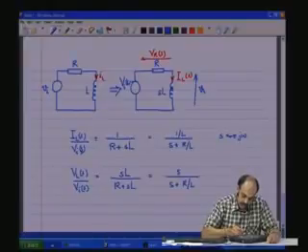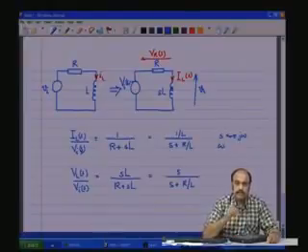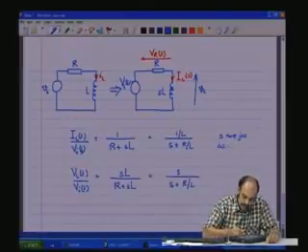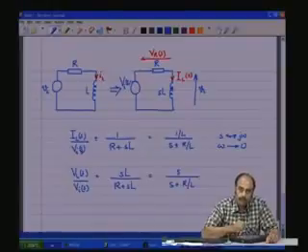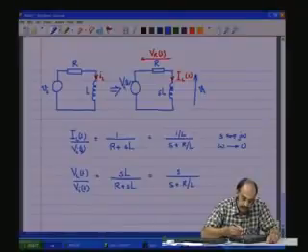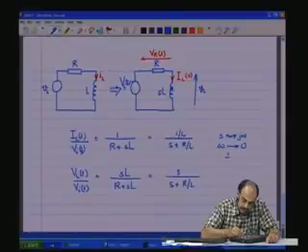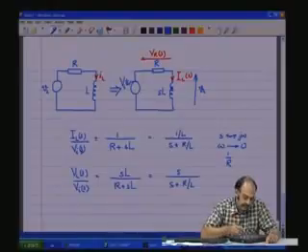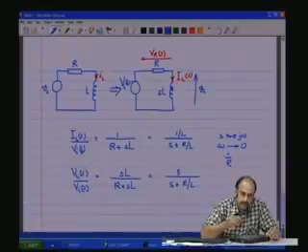So, when we give an input step, as it starts going towards the steady state, that is omega starts tending towards 0, that is pure DC, away from the transients, this will start going towards 0, and then you will have 1 by R as the scaling in this case, that is IL by VI would be just 1 by R, or VI, whatever the input VI divided by R would be the gain.